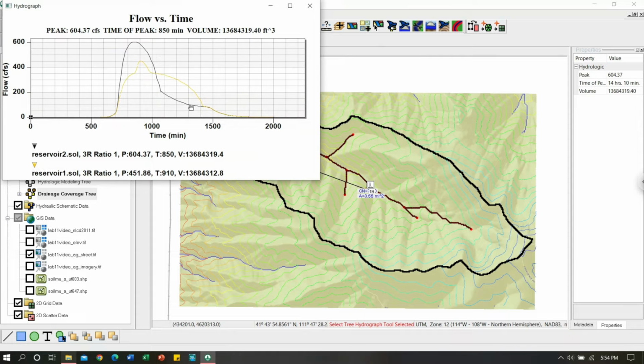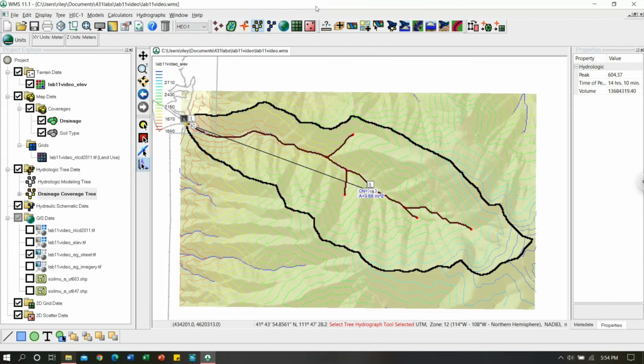In practice, you're going to have constraints about maximum discharges or minimum discharges to protect the aquatic organisms that live in the river, or perhaps you're going to try and maximize the amount of head that's on the orifice if you're trying to generate hydroelectric power on it. We're not providing you a specific use case, so you're at liberty to choose a design and therefore a reservoir design and therefore output hydrograph that you think is best for this scenario. So I'm going to close this out.